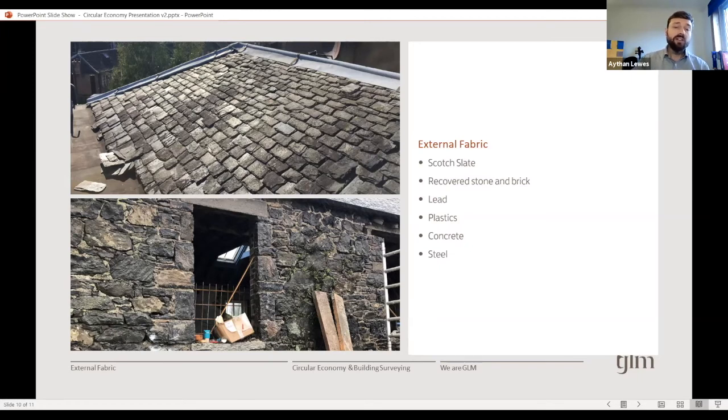The photo below it is a stone which went into a new window opening in a byre on Mull. The stone was quarried by locals within a mile or two of the byre and installed into the floor. During conversion, the floor was to be insulated, so the stone flags were repurposed into these rybats. The flags could be taken up so easily because of the weak mortar in which they were sat. No hard cement binder, no adhesives, no nail fixings. The cost of moving materials to Mull drove the decision to repurpose what was on site rather than buying new. Again, we see the need for alignment with commercial aims to create the conditions for circular practice.